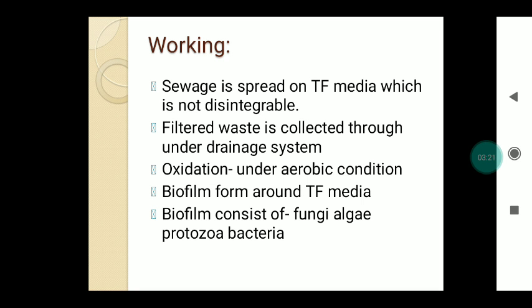The working of the trickling filter is that the sewage is spread over the trickling filter media, which is not disintegrable. That means the decay or decomposition of the filter media is not easy, so that type of media we have to use for this process. The filtered waste is collected through the underdrainage system and is oxidized under aerobic conditions, and a biofilm is formed around the filter media.